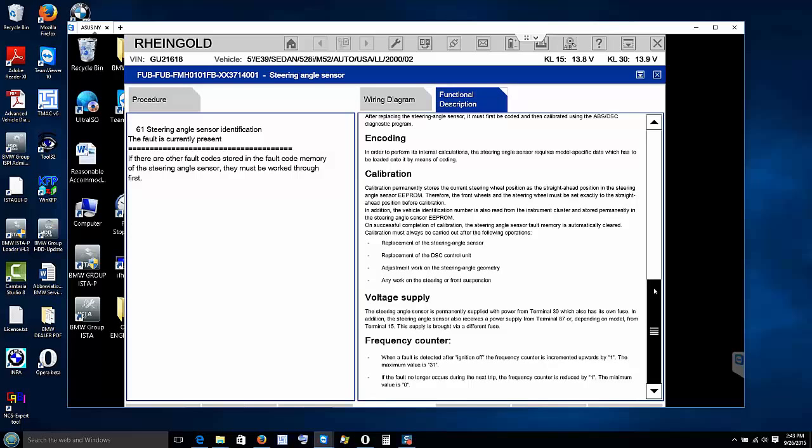So we don't want to keep messing around with the steering and start the ignition key 31 times, all right? Because it's going to put some form of a lock on it, you know what I mean? And we have to reset that and so on. So what we're going to do now, we should copy this information right here, and then we will save this inside of the XPS document so we can read it later on one side of the computer desktop. And then, you remember when we go to the DSC unit and we do ECU call-up function and we see what the angle of it was at 0? Right, okay. We're going to go back there and make sure it is at 0 and nobody touch the steering,